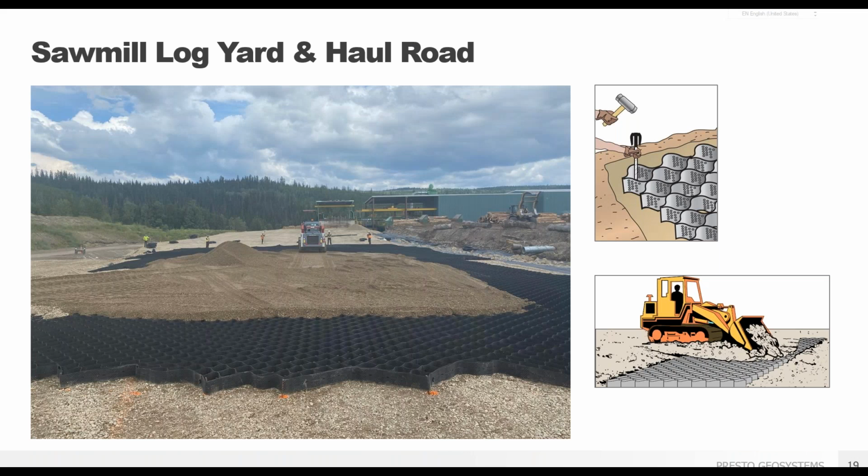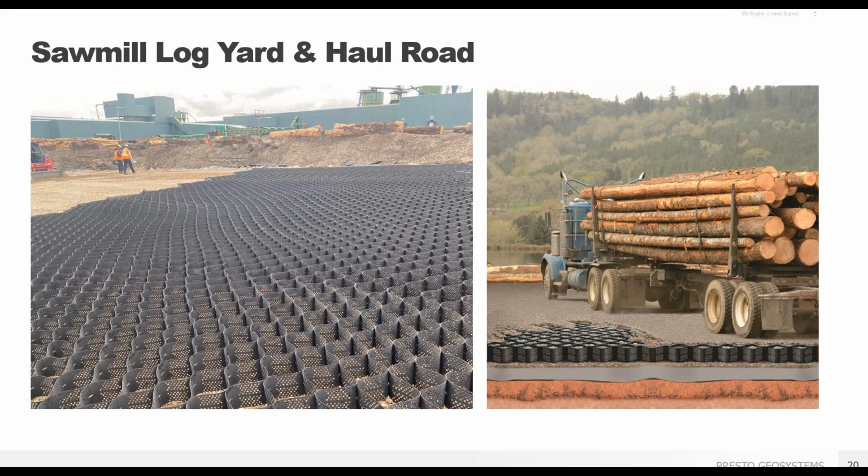This was a project for a sawmill in Canada. Spring snowmelt and fall rains cause flooding and soft, challenging ground conditions in the infeed area. In this photo it is great to see how the GeoWeb was placed and held open with stakes at the perimeter, and then the infill was spread. Presto worked with the project owners to develop and design to manage stormwater and snowmelt while providing stabilization and support of the heavy loading over soft subgrades.